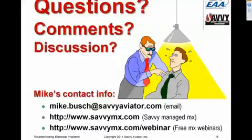I don't want to spend too much time on this because the mags aren't really the subject of tonight's webinar, but just to illustrate this point, we've had quite a few emergencies declared because of magneto failure, and specifically because of magneto distributor gear failure, where some teeth strip off the plastic distributor gear in the magneto, and the magneto starts firing at random times and causing the engine to go berserk.